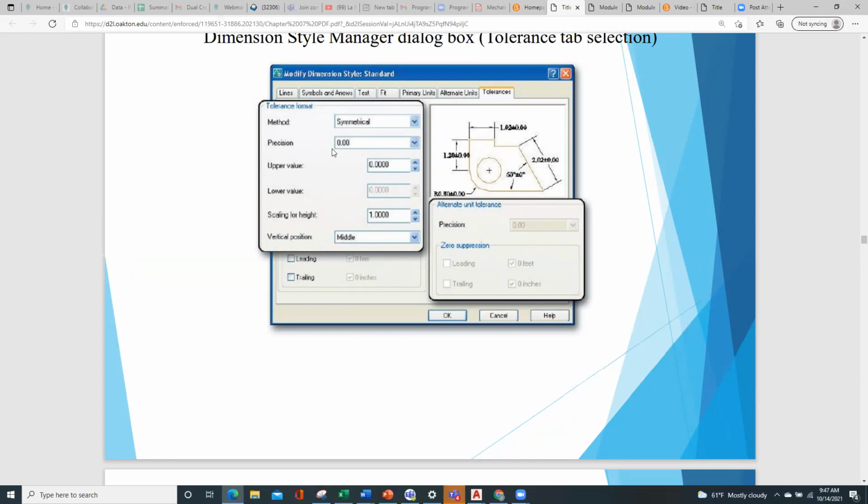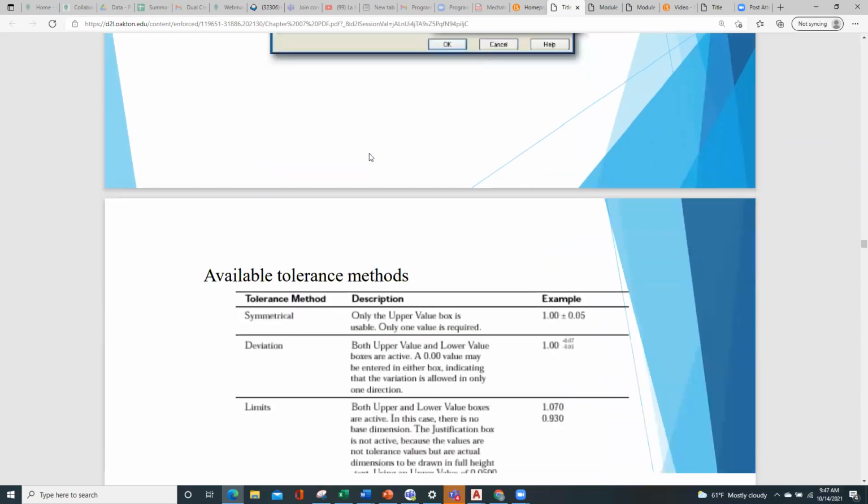And so as we start to work with mechanical design, what we want to do is understand that there is no perfect zero. Everything is a little bit bigger, or a little bit smaller. And by using tolerances, you give the production people the ability to work within that range of measurements. So this part may be 1 inch plus or minus 0.010, 10 thousandths. And that way, if he makes it 1.005, it's within tolerance and it's an acceptable part. And so that's a very common practice.